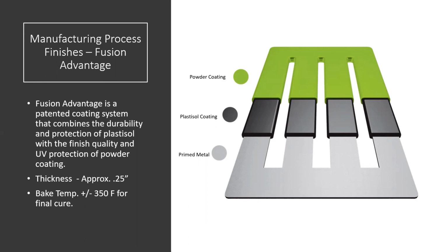So it's the same thing. It's a polyester powder, applied electrostatically, the same process. Which company they're using for their powder coating supplier, I'm not sure, but it's going to be pretty much the same process. There's no difference. The difference is probably going to be what's the base material being used, which I'm familiar with that chair. I think it's a cast aluminum chair, so you're powder coating over top of cast aluminum in that case.